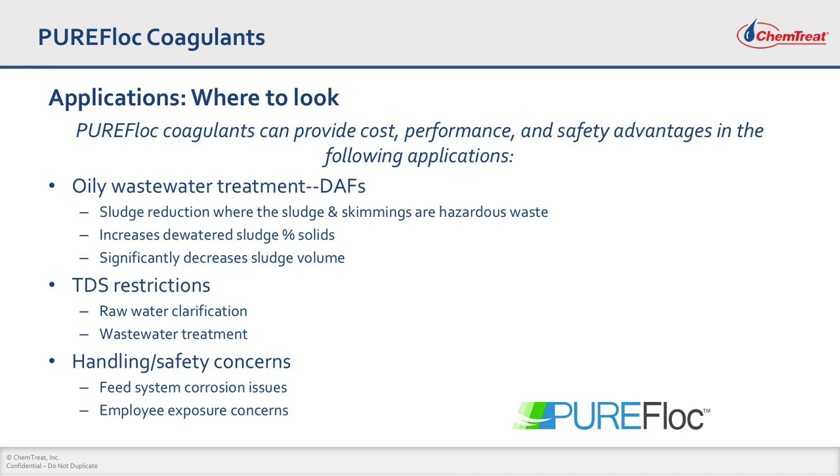Also, you can use these products in applications where there's a TDS restriction. Because these products have low to no sulfate or chlorides, they are ideal for those applications, such as raw water clarification or even just wastewater treatment where you have an issue with TDS restrictions. And then, of course, the handling and safety concerns. They're not inorganic, don't contain chlorides and sulfates, and are not corrosive for your employees to handle.